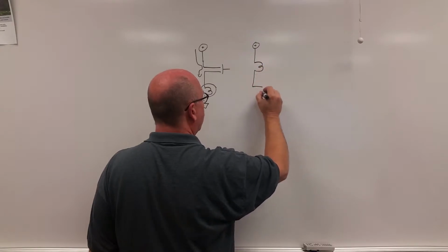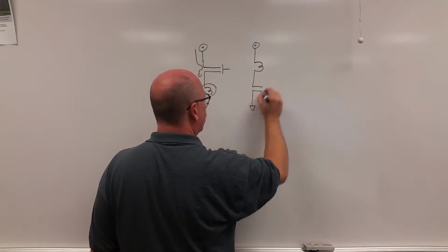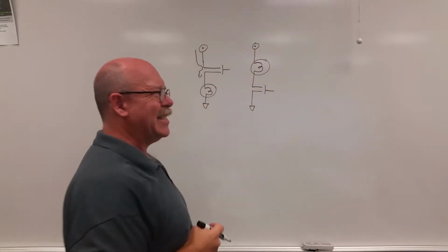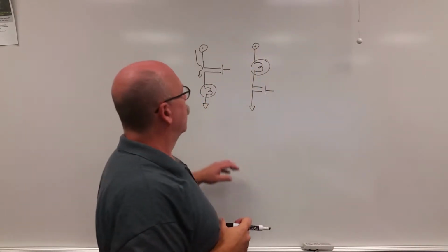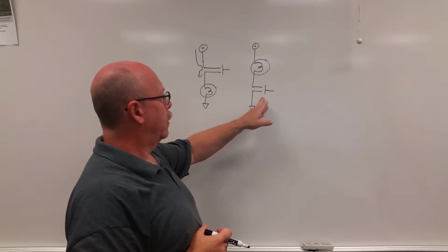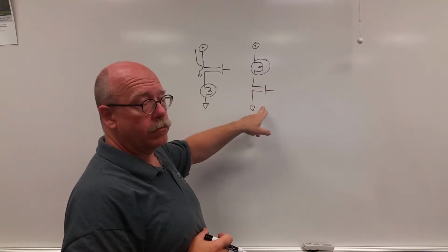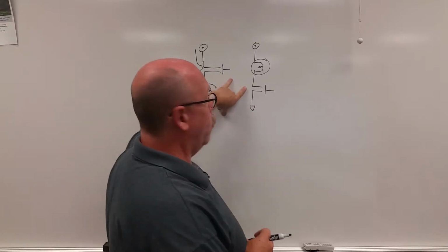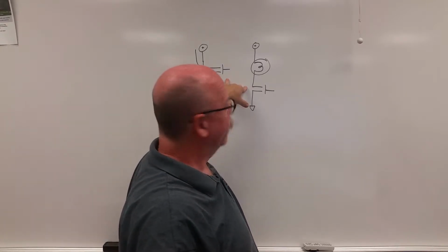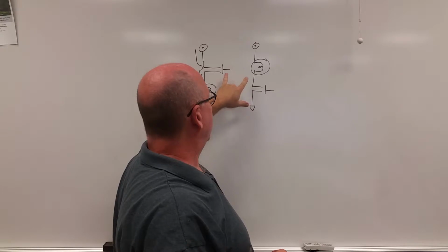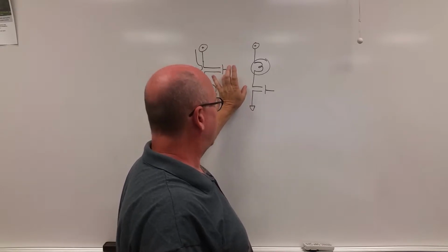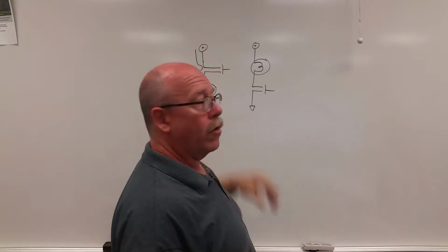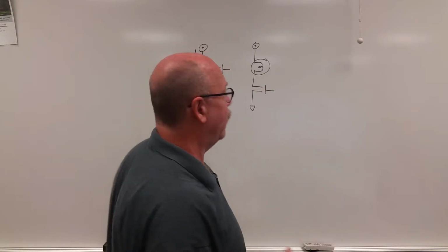By swapping the position of the switch and the bulb, I'm now turning this into a sinking circuit. This means that I sink the bulb to ground. There are several situations where it doesn't matter which way you put these. For instance, if these were dry contacts, as I have drawn here, just simply a switch, the switch can be placed anywhere in the series line and it doesn't matter.